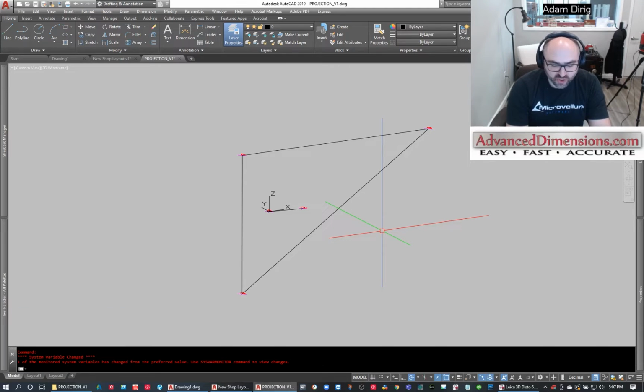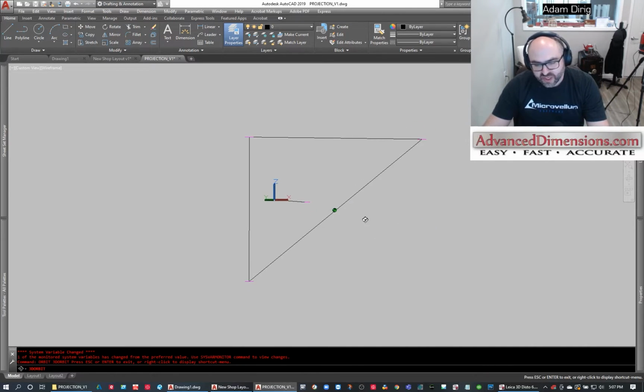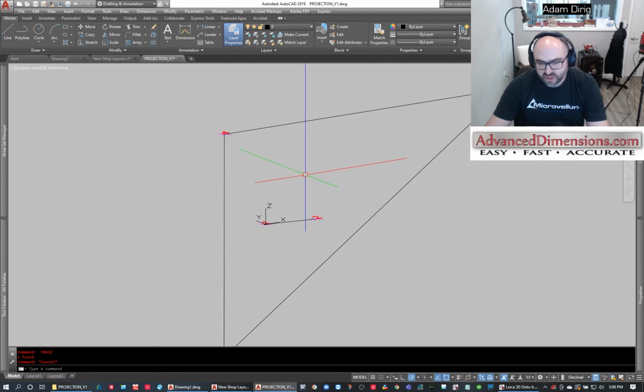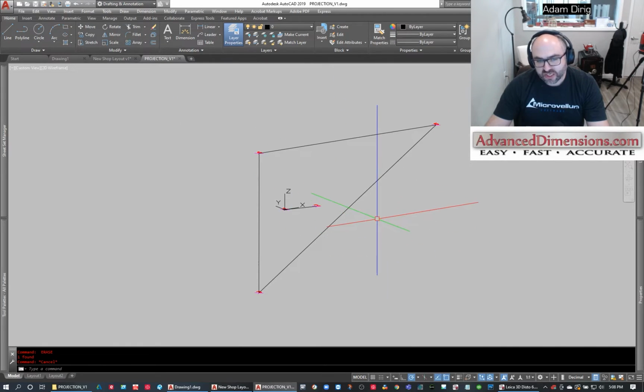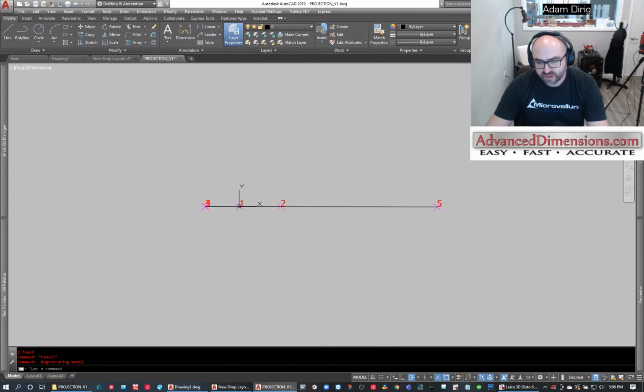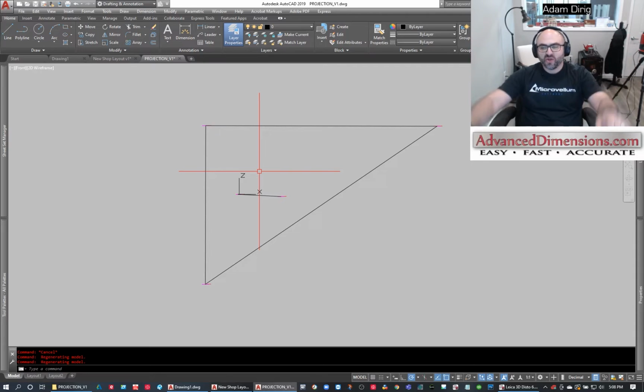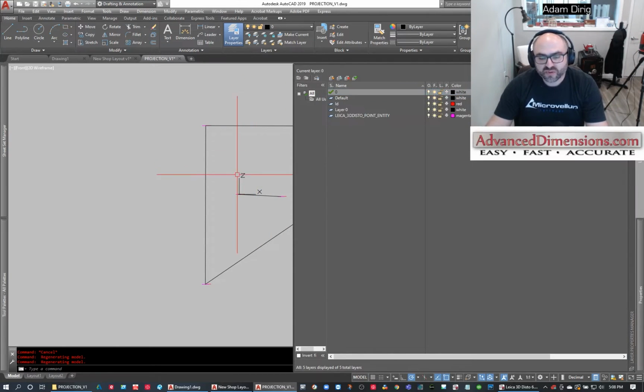And everything is good. So when we look at this, we can go, okay, I want to project points here and here and here. But there's a problem with that thought. When we set up our projection file, we set it up from the top. This is the way the Disto reads that file. So we can't set up our projection points like they were if we were looking at the wall in elevation, because this is the front view. That's going to give us trouble.